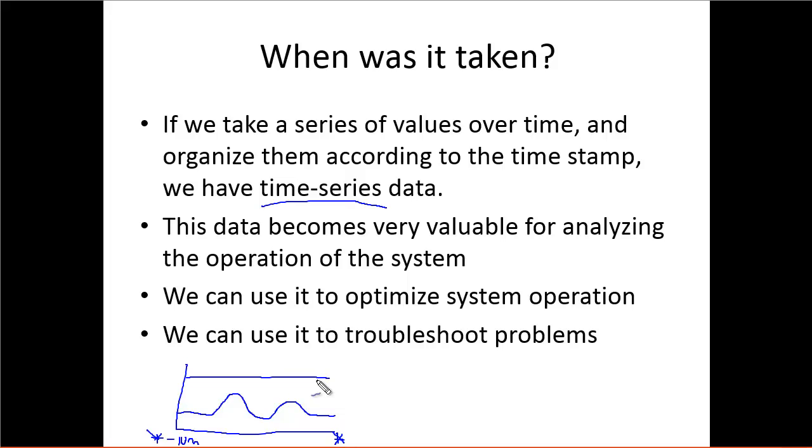Let's say there was a problem, and I go back and look at my trend and I say, oh yeah, there was this upset. This happened right here. Well, that's valuable in helping me troubleshoot what's going on. And maybe if I can display this value and 5 or 6 other values from the electric grid, maybe that helps me figure out what's going on. Maybe I could have a trend here that shows a breaker that went from closed to open, and after that happened, I had some sort of disturbance.